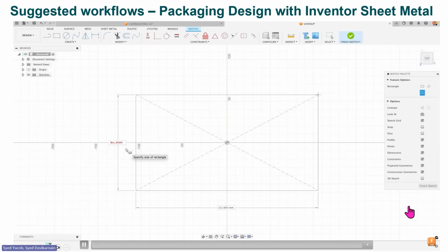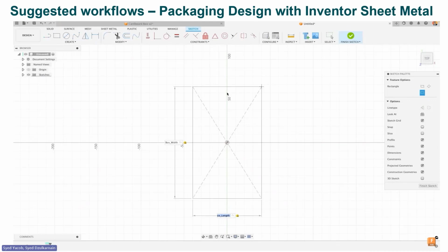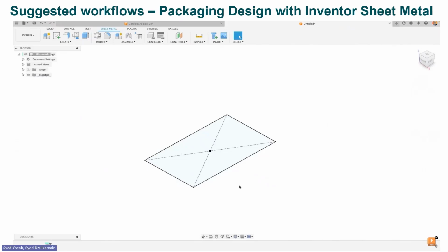Okay, so as an example, we obviously will start with very simple sketch or shapes. You can see that instead of having dimensions with figures, my dimensions have already been configured to use names, like box length, box height, box width. This you can configure in the parameters, so that it becomes standard and you're not adding a new dimension every time. So you can repurpose the so-called parameter.